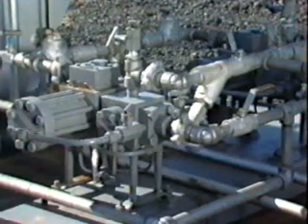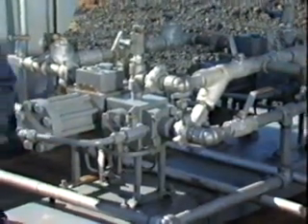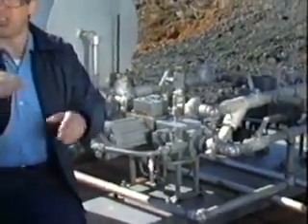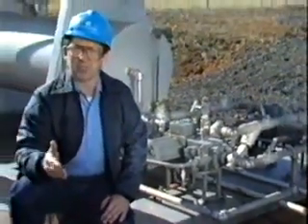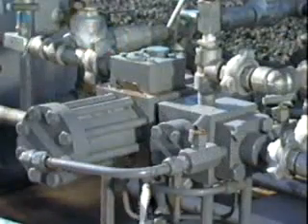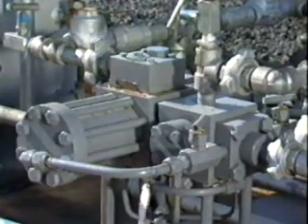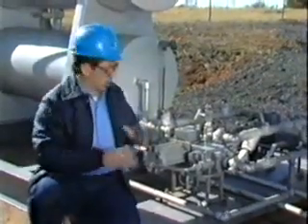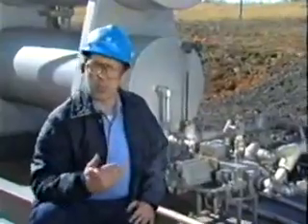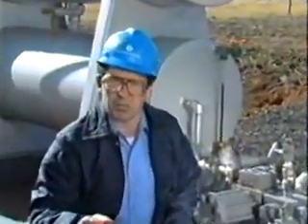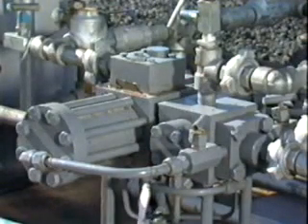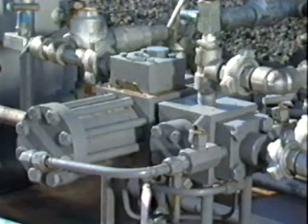Most small dehydration units use a fluid-driven pump, while larger units generally use electrical-driven reciprocating pumps. In either case, the pump is a critical part of the unit because it has the only moving parts in the system. Before the rich glycol enters the pump, it passes through a strainer to remove large particles. Leaks can be a problem around glycol circulation pumps. Proper packing gland maintenance and the use of the manufacturer's recommended packing can minimize this problem.